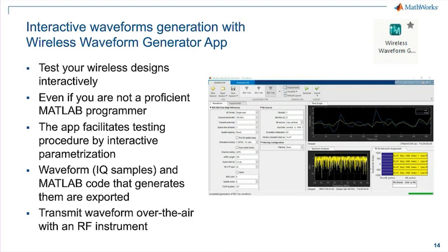And there's a wonderful export button. You click on that, and every line of MATLAB code that generated that corresponding 5G or LTE or wireless LAN waveform will show up as MATLAB code. So you can take the MATLAB code and run a for loop around it or a while loop and test multiple of these parameters for large-scale testing of your devices. That's a very wonderful feature we have added here in our presentation.